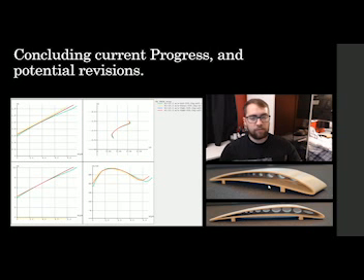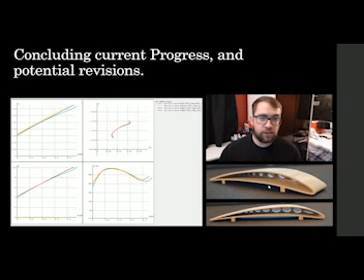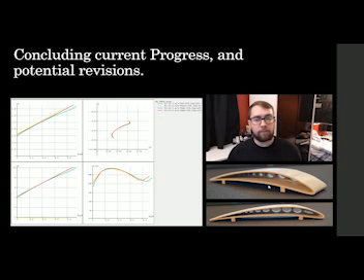So the aerofoil successfully achieved lift at 15 meters per second and would successfully carry a 500 kilogram mass at 28 kilometer altitude. The drag coefficient is 0.002 away from being the lowest achievable, while flying at 0.65 lift coefficient. To improve further, firstly, a wing incidence of negative 0.15 degrees is needed for ideal lift coefficient to be at level flight. Bending moments need to be reduced with tapering.